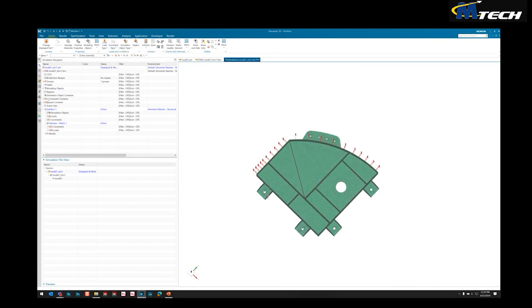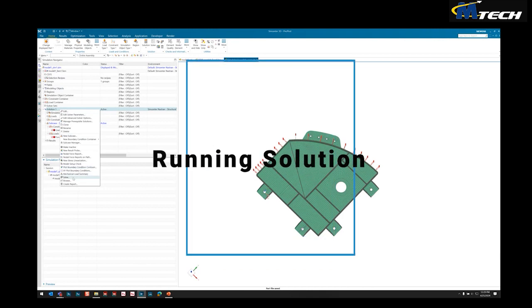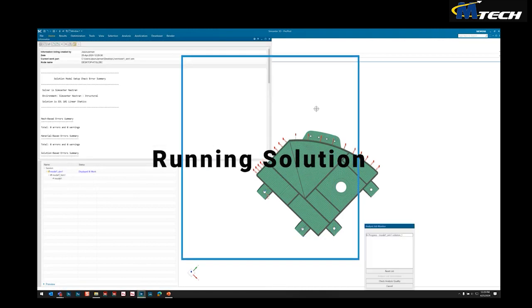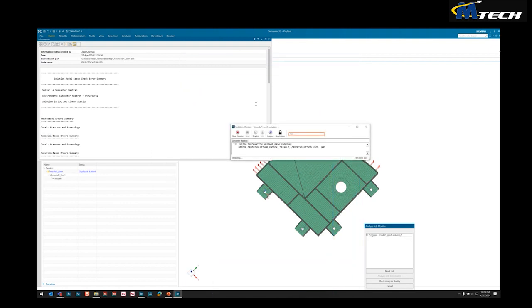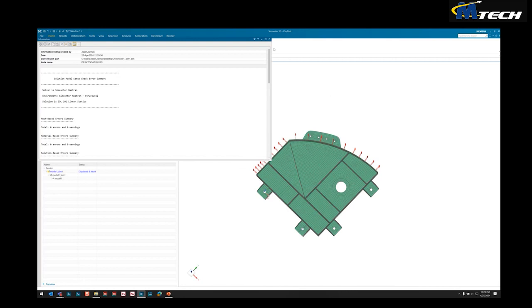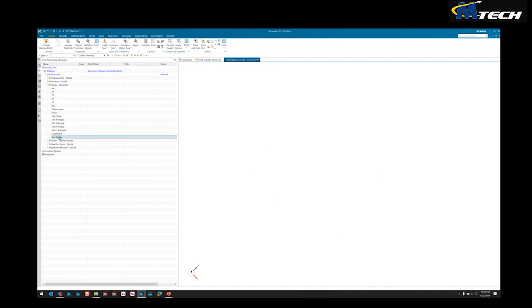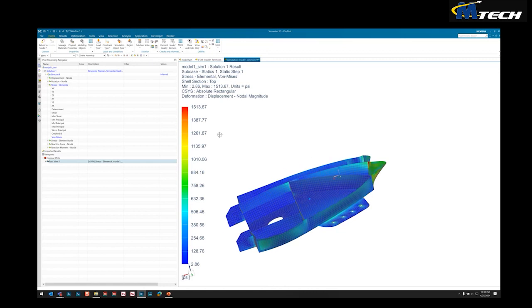And we set up the solution in the beginning. So our solution is already here. It's already got our active set from our constraints. We'll go ahead and save, and then we'll run the solution. Should just take a second to solve. Cancel and hit cancel. And then we'll go into our post-processing navigator, and we can create an elemental stress contour plot of the von Mises stresses.